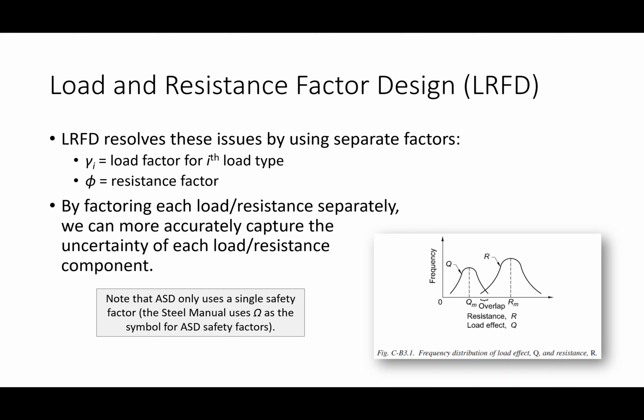Now I'm going to talk about this a little bit on Friday because I'm going to make this point a little bit more clearly. But if you open up your steel manual, I do want to mention a couple things about ASD versus LRFD. In steel design, you still have the option of doing both. If you go to concrete design, you're only doing LRFD, okay?